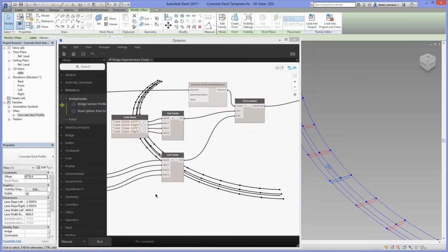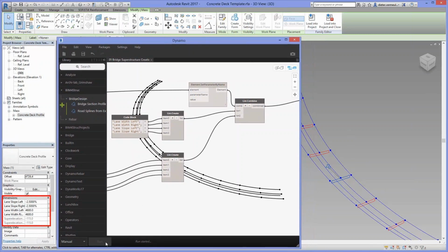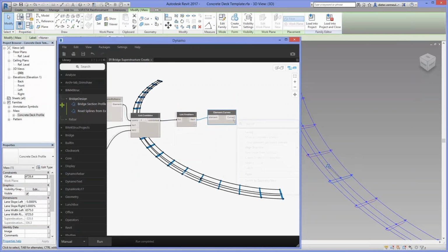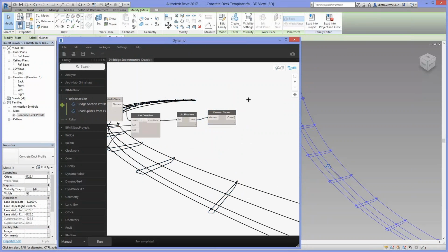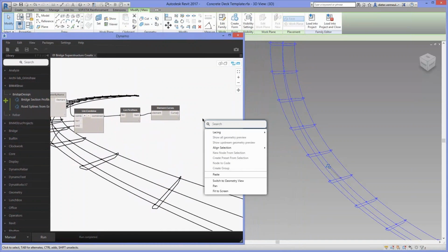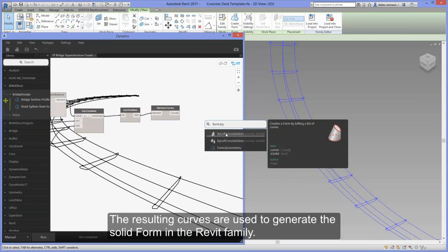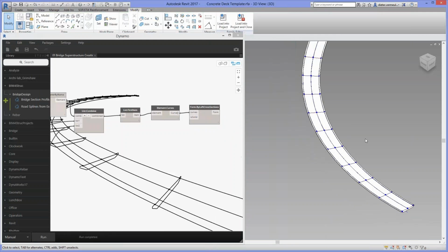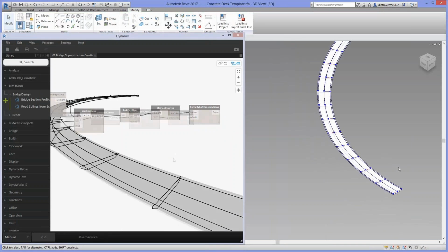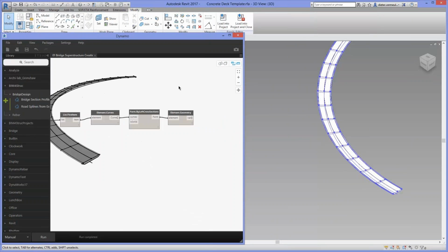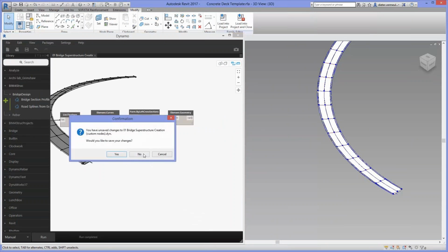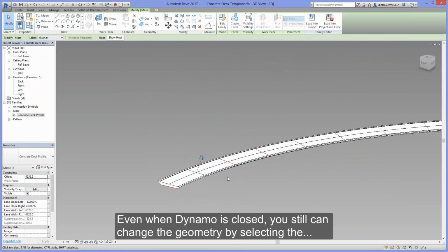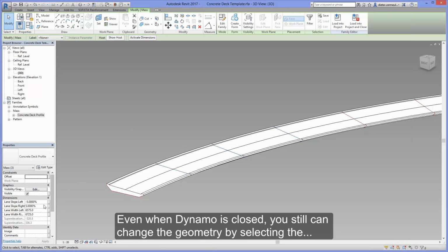And now I am telling the system that what I want is that this typical cross-section will be hooked to these lines, and you saw that the system knows what to do, and the system will automatically apply the width of the road and the super elevation of the road based on what has been done by the road designer. And the very same model has the bridge designer, and he did what we call solids, and these solids are based on what the road designer did.